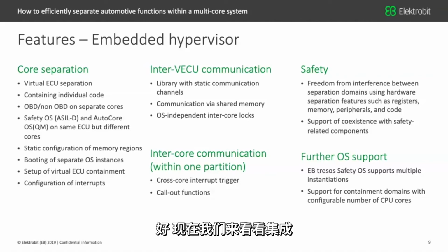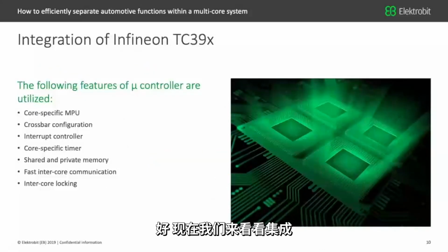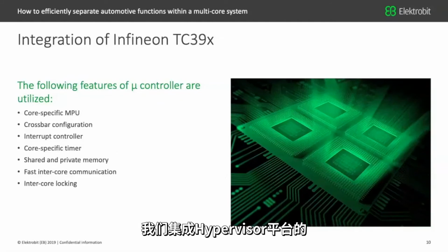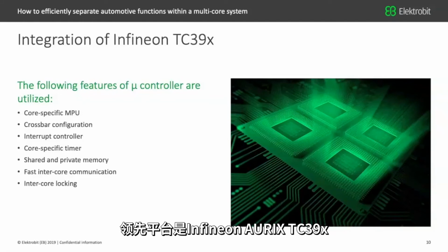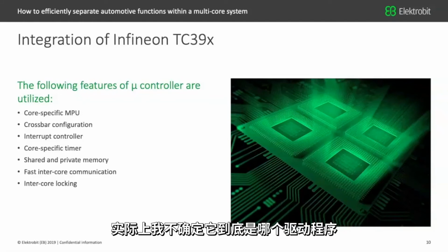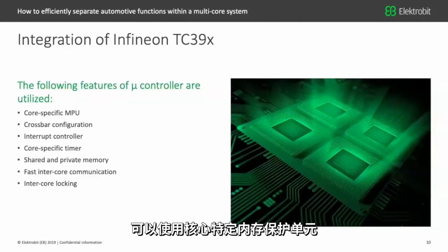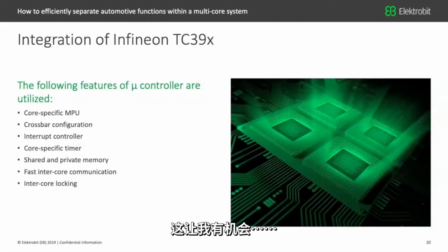Okay, now if we look at the integration, what we have done or are doing right now. Our lead platform for the integration of the hypervisor platform is the Infineon Aurix TC39x. I'm not sure which derivative exactly, but important is the usage of the core-specific memory protection unit, which is available on the Aurix.